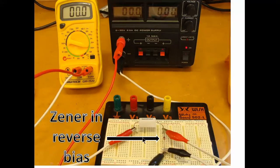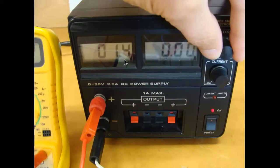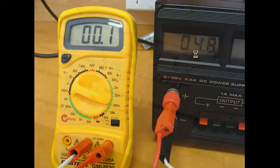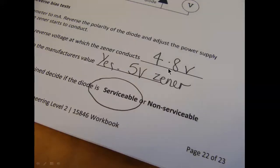In reverse, there's our cathode there, connected to the positive. What we're looking to do is to adjust this voltage on the power supply until we get a current flow. And this has been adjusted to 4.8 volts, and I'm just starting to get current flow, 0.1 milliamp. Anything less than this 4.8 and there's no current flow. I'm going to record that there, 4.8, and the Zener is actually manufactured as a 5 volt Zener, so that's very close. That's within the manufacturer's specification. So again, I would say that Zener diode is serviceable.